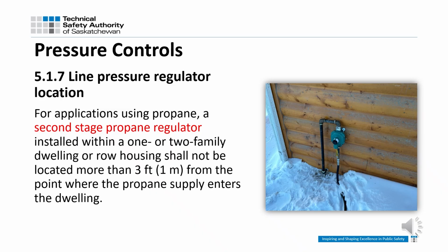In this picture, it shows a second stage regulator installed in a typical fashion in the province. The hose used for a temporary line between the propane tank and the second stage regulator needs to be replaced in spring with a proper underground line when the ground thaws. Paint the exposed gas line as required in 6.16.1, plus refer to Table 5.3 before installation for clearances from the regulator.